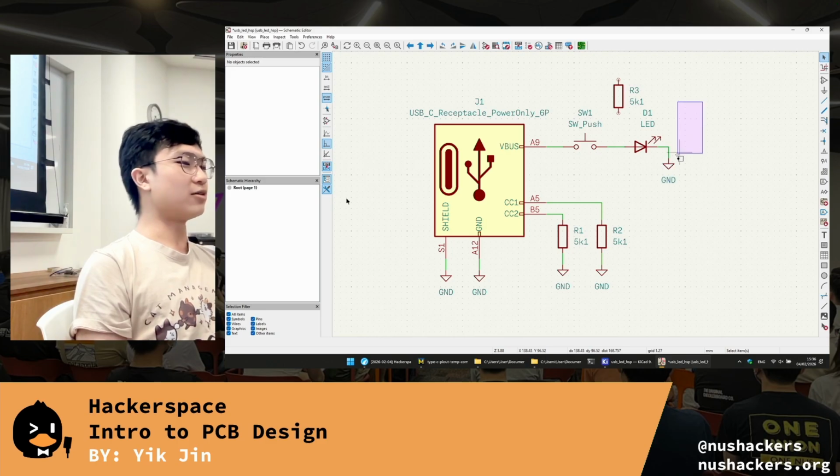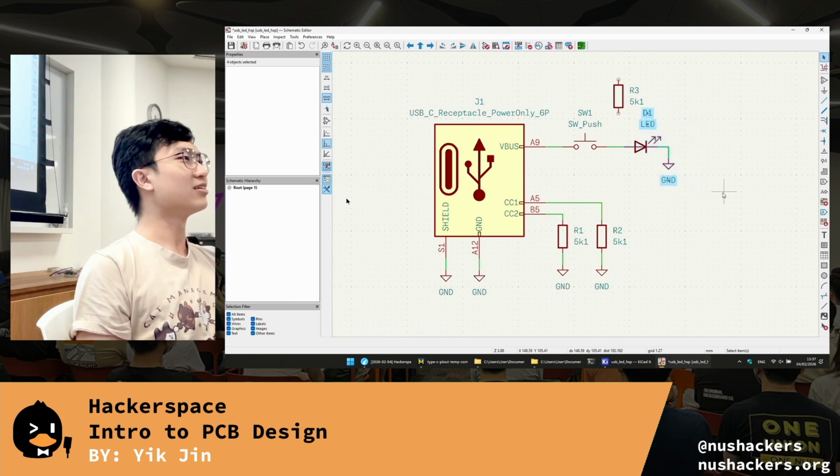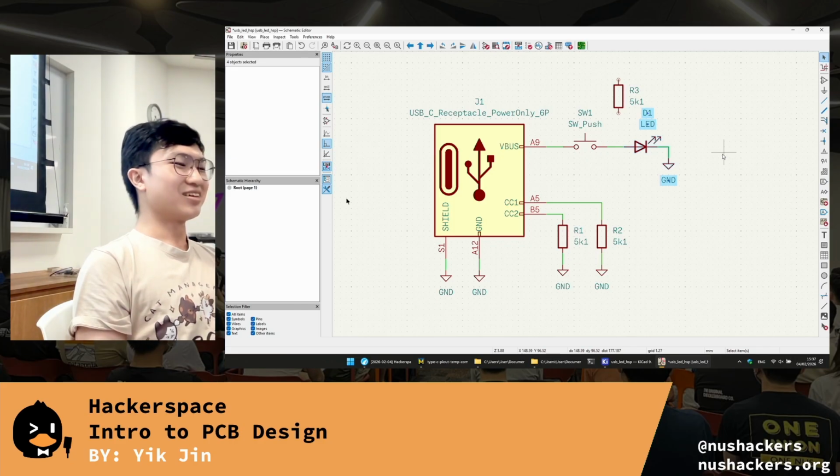If you draw from right to left, everything that's touching the box at all will be selected. So if you do this, same as just now, LED partially selected, ground fully selected, you release, LED will be selected. These are just shortcuts. How do you tell the difference? Which selection mode you are dragging?